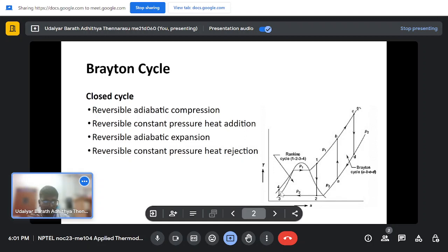If you see, there are two constant pressure lines, P1 and P2, which go inside the phase boundary into the subcool region and the superheated region, and there are four vertical lines. All our vertical lines denote constant entropy lines, or a reversible adiabatic process, or isentropic process.